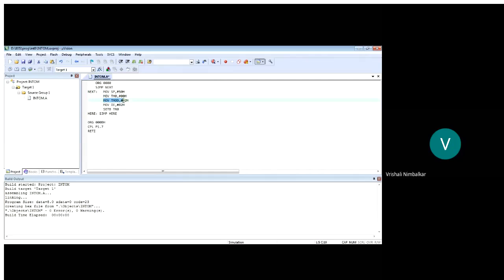Then initialize the TMOD register 02 hex, mode 2 auto reload. Then enable timer 0 interrupt, MOV IE, #82 hex, and then we start the timer. So that count up begins. And then we wait in an unconditional loop, a never ending unconditional loop. So that was our main program.